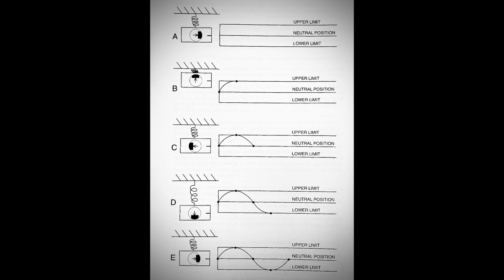And what Paul is trying to emphasize here is that each one of the components in the machine is going to have one of these vibration signatures, and they can all work together in time at one specific natural frequency, at which point all of those excitation forces are working together at the same time and can really amplify the amount of severity of vibration that you're measuring.